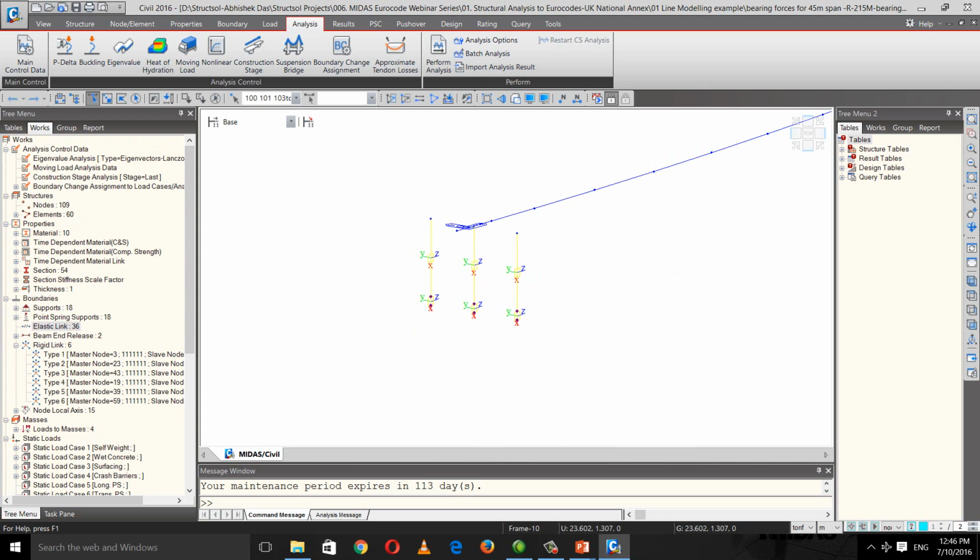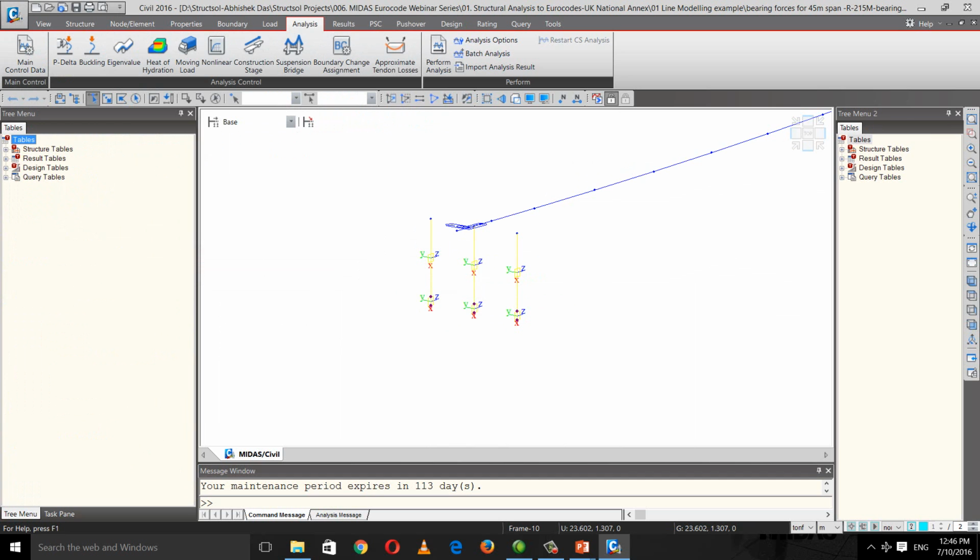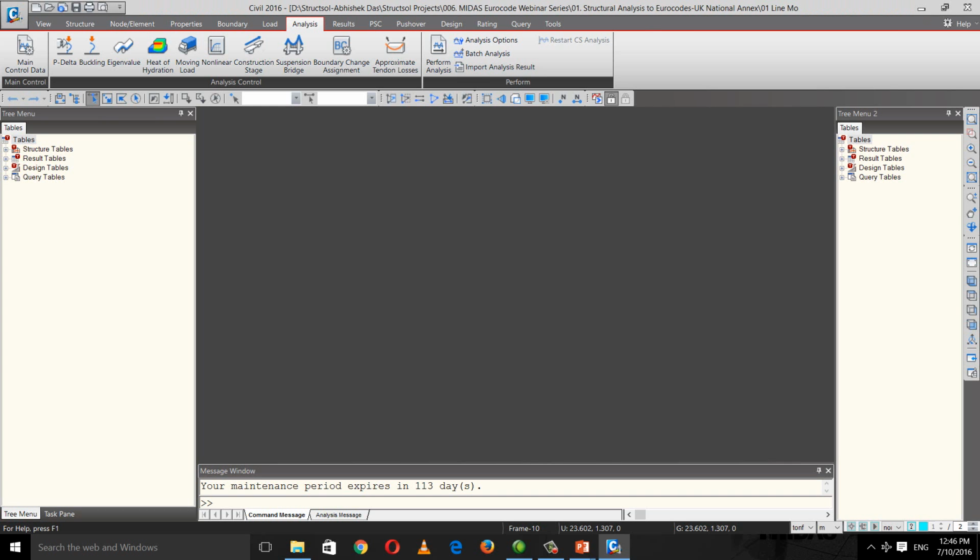And the second case, as I said, can be simple design checks. We may have very complex plate models, such as a composite plate girder bridge, where we have modeled the deck as plate elements. Now when we use plate elements for our analysis, the automated design checks that are there in the software don't tend to work directly.